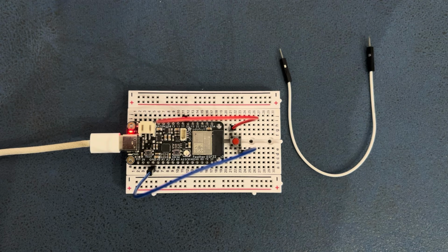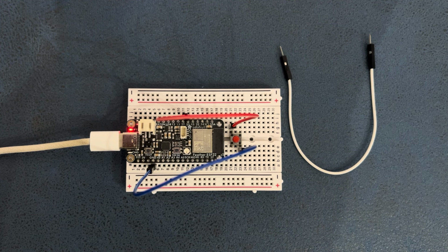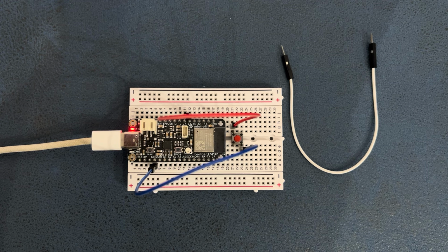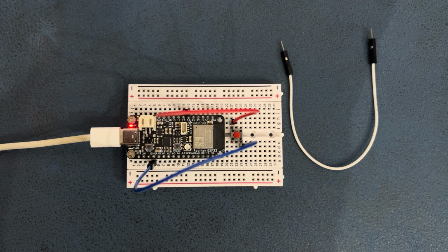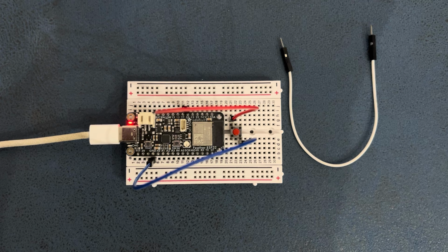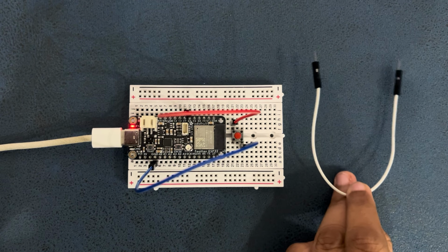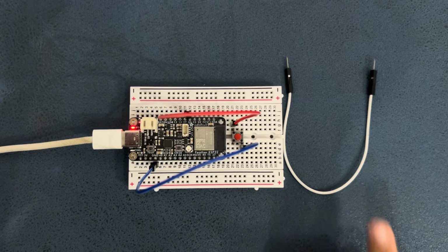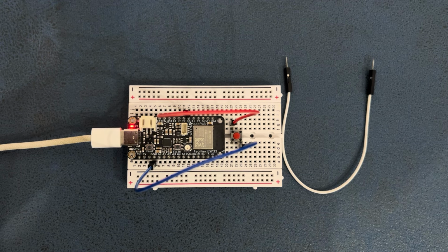Next, the NeoPixel LED is also an onboard LED. It is powered using GPIO 2 and controlled via GPIO 0. This LED is used to indicate touch input. It stays off when there is no touch. It turns green when touch is detected. So for touch input, I am using a jumper wire that I will connect to GPIO 4 and I will keep the other end open